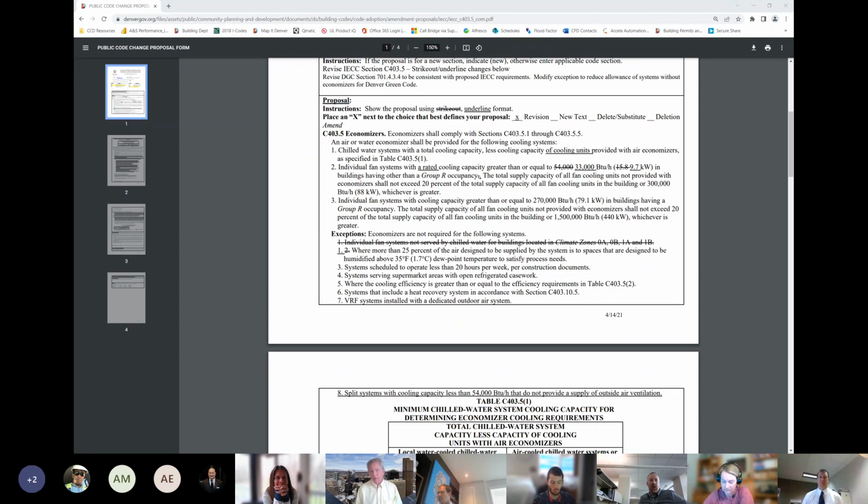First of all, understand what VRF systems are. There's multiple types of VRF systems. There's VRF systems that are essentially a cooling only system that just happens to have multiple evaporators connected to the same condensing unit. That's a VRF system. It's classified as a VRF system in AHRI by the manufacturers and everything because the refrigerant flow is variable based on the load. That is a cooling only system.